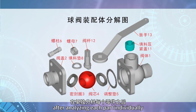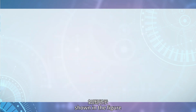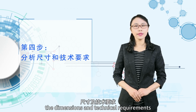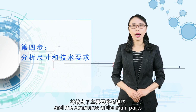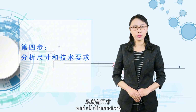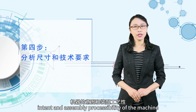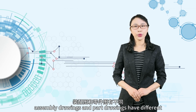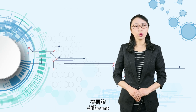After analyzing each part individually, the shapes of all the parts of the ball valve are as shown in the figure. The fourth step is to analyze the dimensions and technical requirements. Based on the analysis of the assembly relationships and the structures of the main parts, it is also necessary to study the technical requirements and all dimensions, to further understand the design intent and assembly processability of the machine or component. Assembly drawings and part drawings have different functions, so the requirements for dimension labeling are also different.